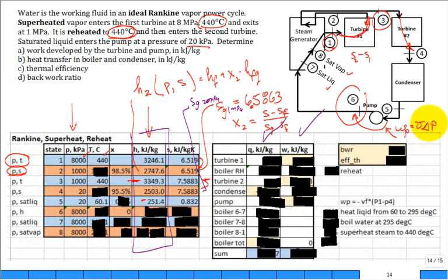I encourage you to look at that last time at the end of chapter 6. When you have a specific volume, pressure change, and it's isentropic, it boils down to very simple VDP. This is the specific volume of saturated liquid at state 5. That's what's coming into the pump. And then this pressure change is the high pressure on the outlet, P6 minus P5.